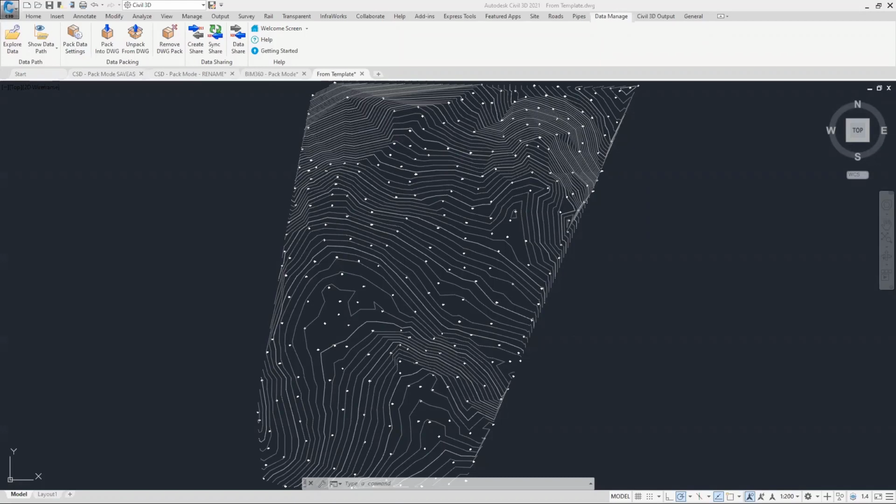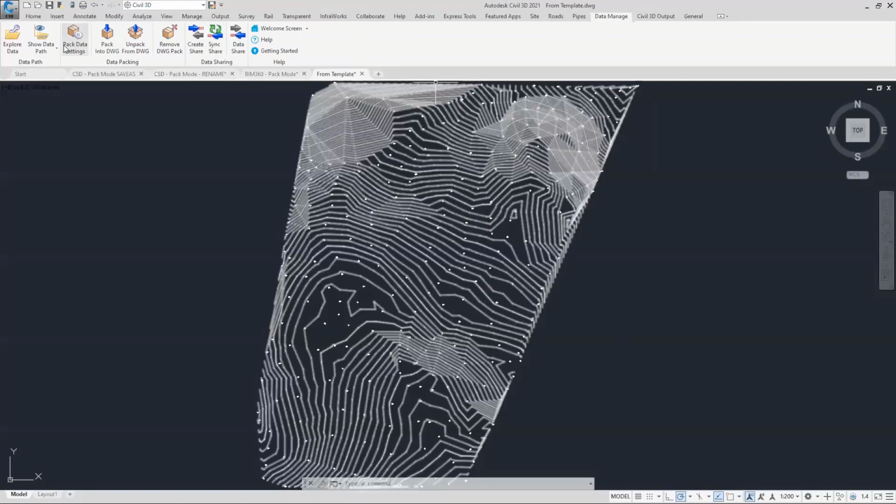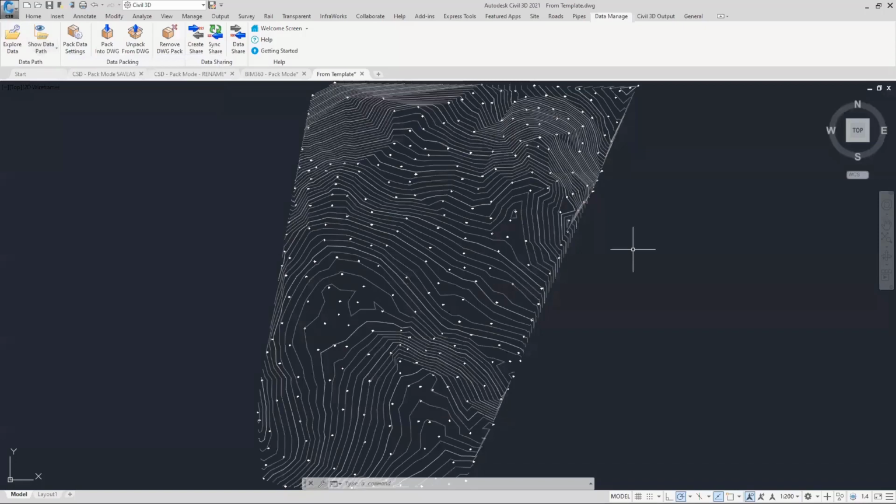Okay, so yeah, there's actually a good question regarding files. In regards to file size, what'll actually happen is we do have a limit, and I think that limit of compressed data is 60 meg. So that's 60 meg after it's been compressed. At that point, we will flag a message saying, hey, look, we don't recommend the use of pack mode because we don't want to blow the file up in size. If you've got really large surfaces, you probably don't want to use pack mode.